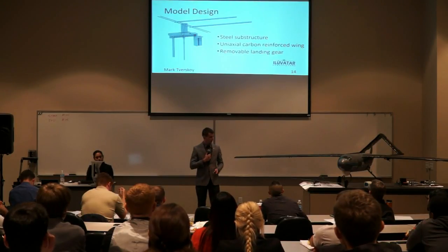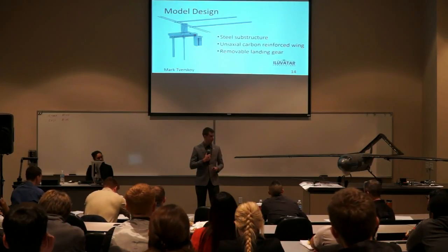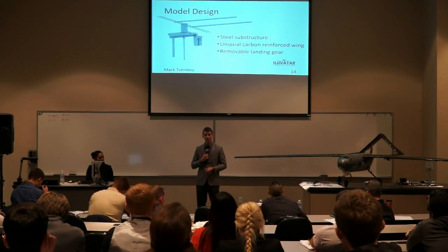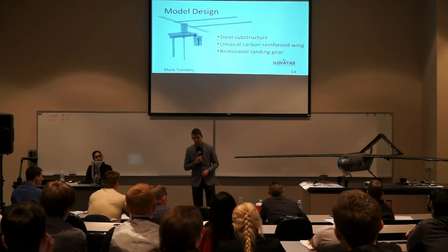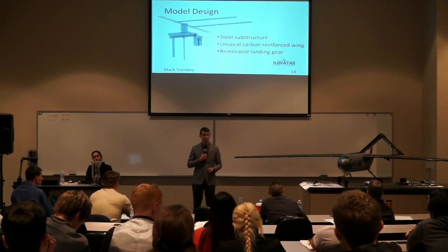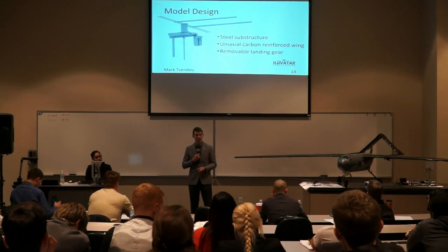The wings were also pretty thin because of our thin airfoil profile, so we reinforced them with a uniaxial carbon strip on the top and the bottom to reduce their flexure. The landing gear was also detachable to test for how much drag the landing gear would actually cause.